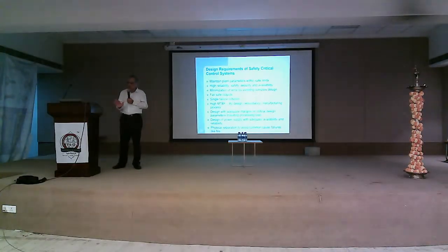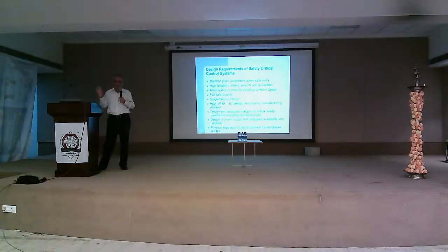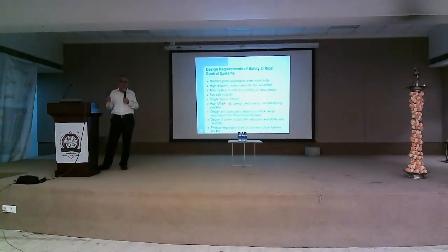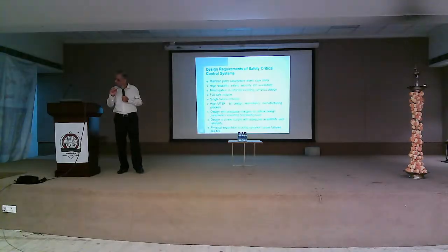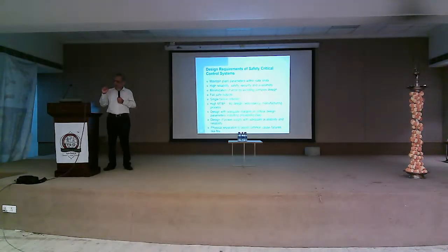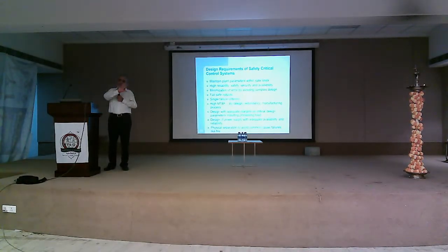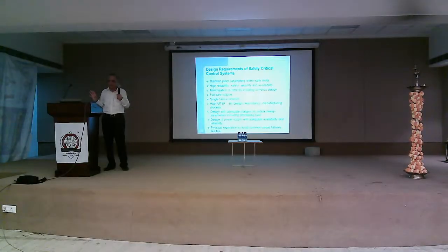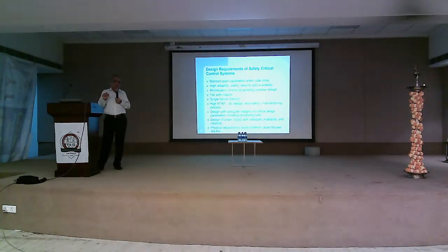So it is a safe condition. Similarly, suppose I am controlling the primary coolant pressure, which is around 56 kg per centimeter square. It is controlled by some input or output valve in the system, and we manage that so that pressure is maintained.